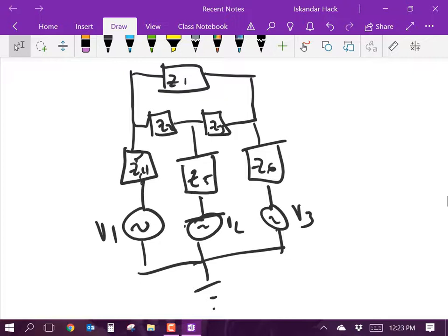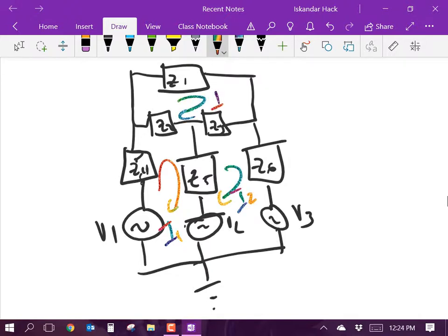But if I draw this all clockwise, I1, I2, and I3, right there. I'm drawing three loops, all clockwise and all internal. I start at the bottom left-hand corner and go across the bottom, and then I go to the right. I just have an orderly way of doing it because things kind of turn out nicely if you do this. No guarantee.